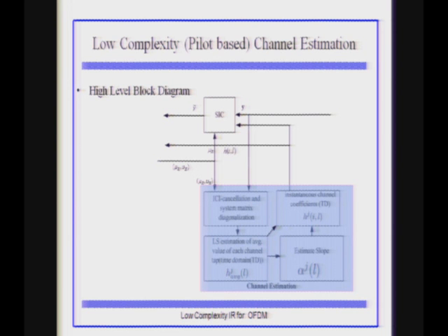Instantaneous channel value, but isn't delay involved? Okay, that's okay in the sense. When we look at the equalizer, say in the first iteration, for any scheme for that matter, let's talk about our scheme, the SIC requires only the diagonal elements for the first iteration. So that can be easily computed. And then after the first iteration, you get all these values, and you do the computation. The moment you have the values available, you plug that in. Until then, you work with the old one.